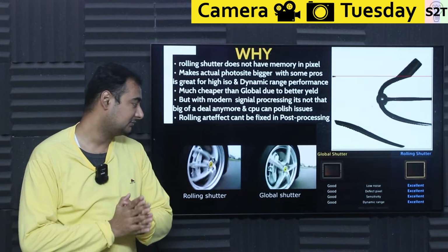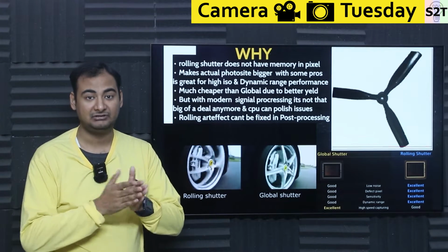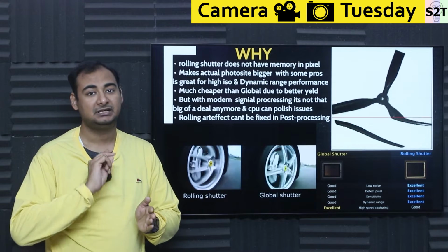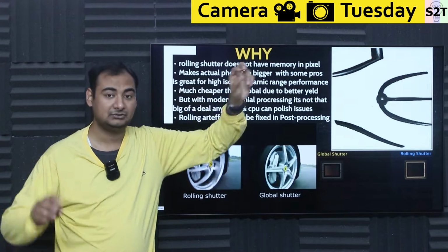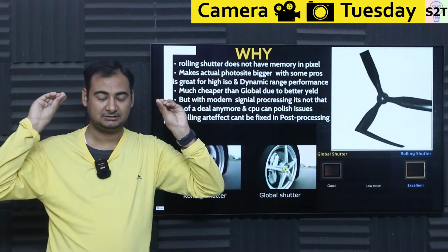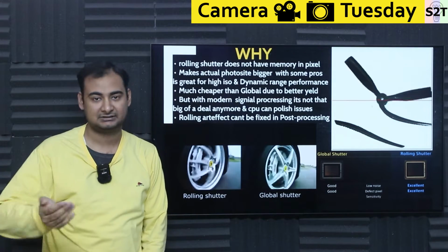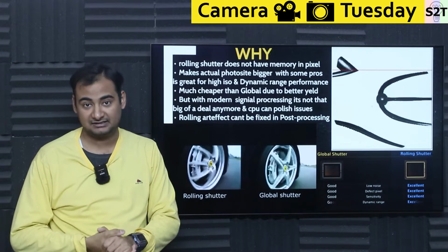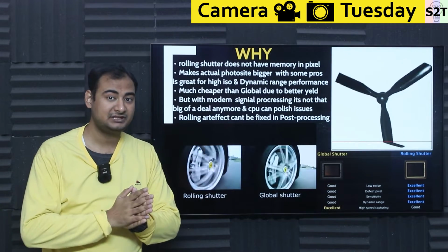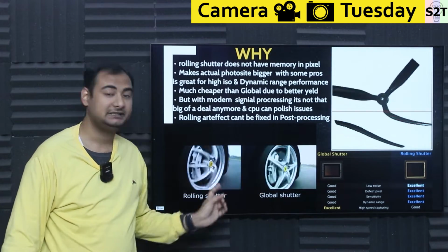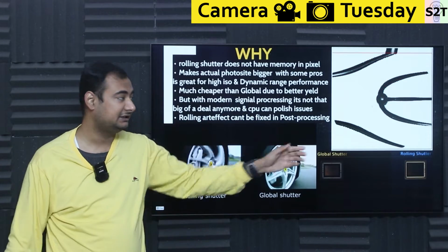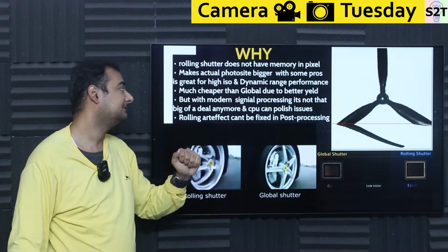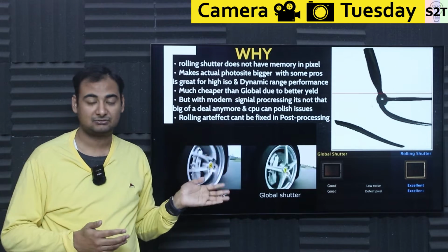However, CMOS was inherently weak in one regard: it read line by line. Basically, row by row, it kept reading the sensor. So there was no impulse. It was like a scanner. Now, the moment you make a sensor big, or even on a small sensor, if you move things fast enough, like a propeller, wheel, or a racket, anything slim and long, and you are moving around, it will literally have this wobble happening to it. So why the heck was it there?